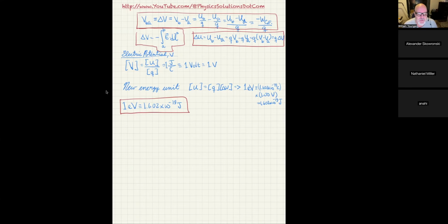A household outlet, you're probably familiar with that. They call it 120. Some people call it 125. That's the ballpark, and it's pretty consistently around 120 to 125. Technically speaking, electricity is what we call AC when it comes out of your wall outlet, but that 120 figure is not the peak. It's not the amplitude, so it would not go up to 120 and down to zero and then back to negative 120. That's not it at all.